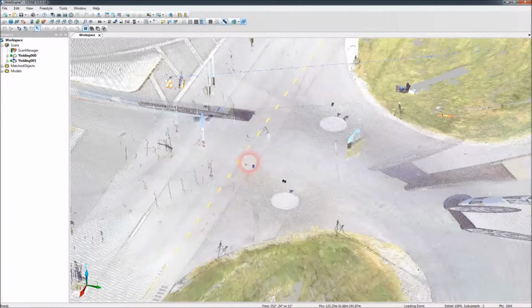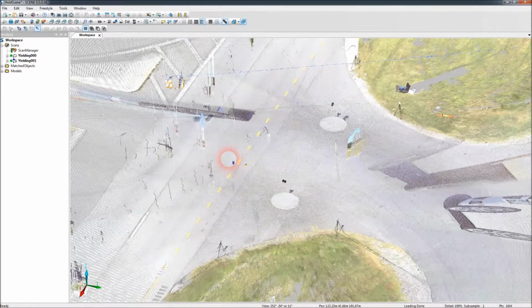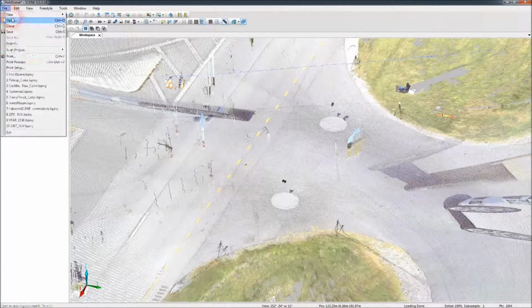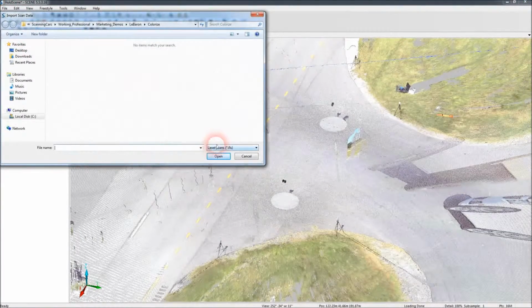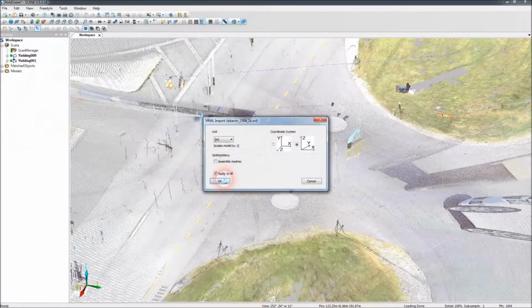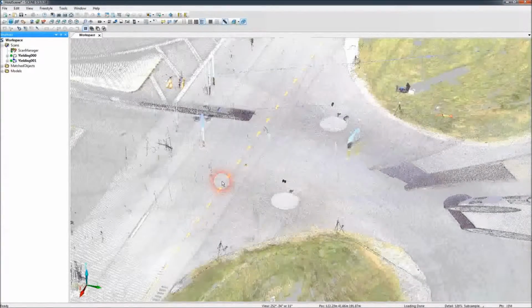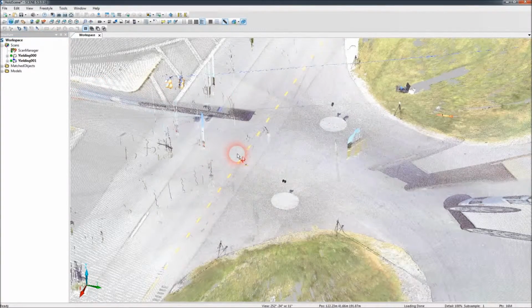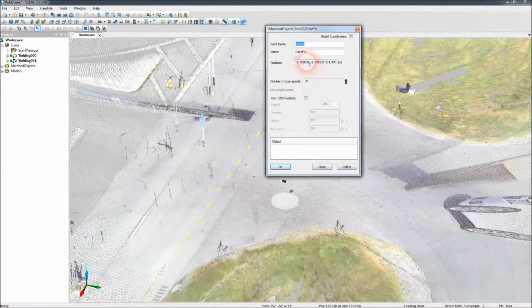I've created this into a scan point cloud because I need to select one of these points. Basically, I'm going to import the model: File, Import, and select a WRL file. I'll click this mid-range one I have, 150K polygons, 2K texture, and import it. It's going to put it right at the origin. If we select one of these points, you can see the coordinates of that point: about -2 meters in x, -3 meters in y, and 101 meters high, which is probably the elevation from sea level.